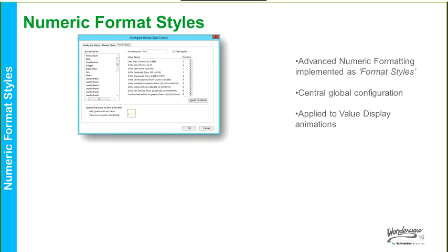The numeric format styles are also a standardization part. Because here we can say, how do I want my values to be displayed? If I have a display animation and I want to show a value between 0 to 1, what's my precision? What do I want to have? That can be set from one place inside InTouch.